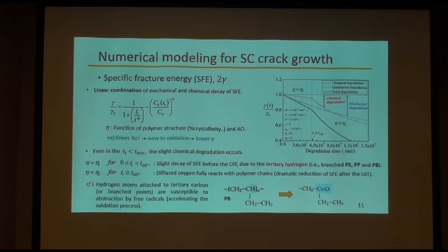We must consider the oxidation induction time in case we simulate the oxidation of plastic. Generally, before the OIT, the diffused oxygen reacts with the antioxidants mainly. However, in the case of polypropylene or branched polyethylene, the hydrogen atoms attached to tertiary carbon or the branched point are susceptible to abstraction by the free radical.